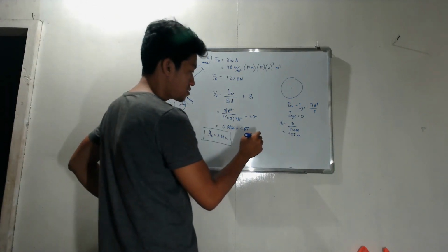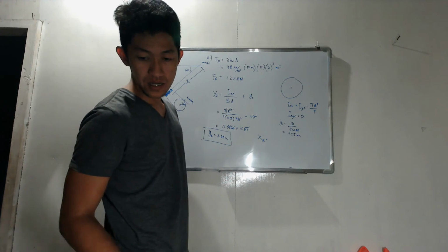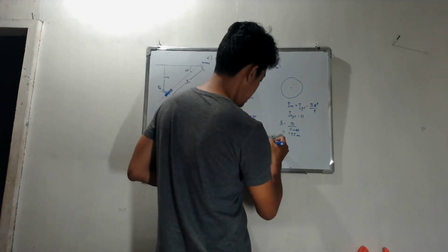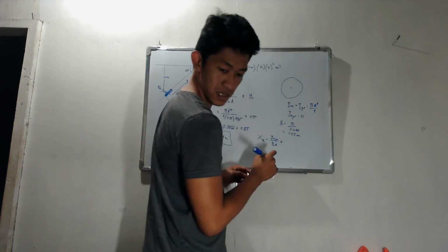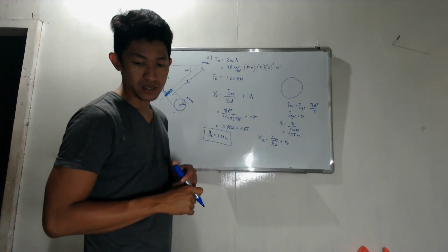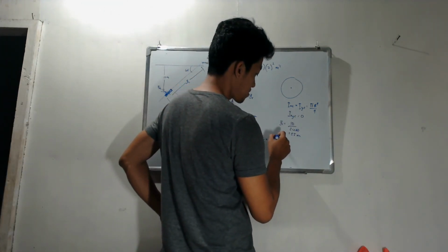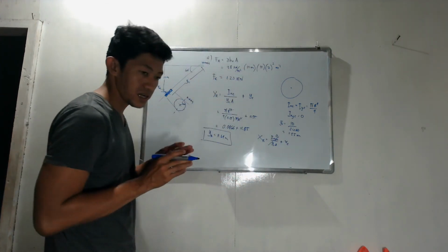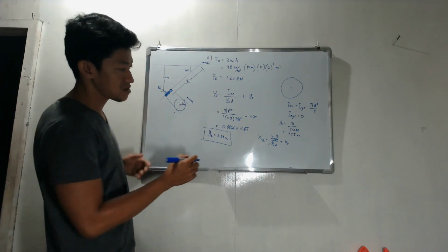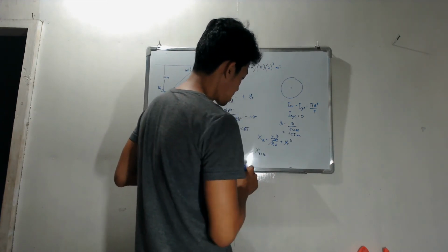And then, x sub R. Its equation is I sub xyC over y sub C times A, plus x sub C. The first term is 0. And then x sub C is how far the centroid is along the x-axis. It is along the x-axis, so it is still 0. Therefore, x sub R is 0.